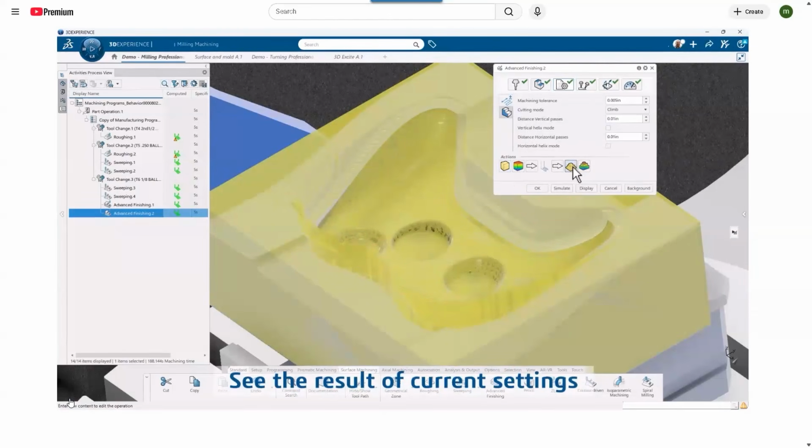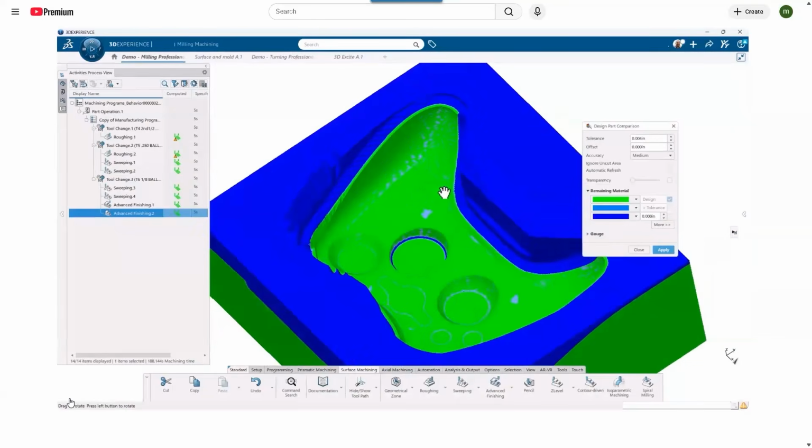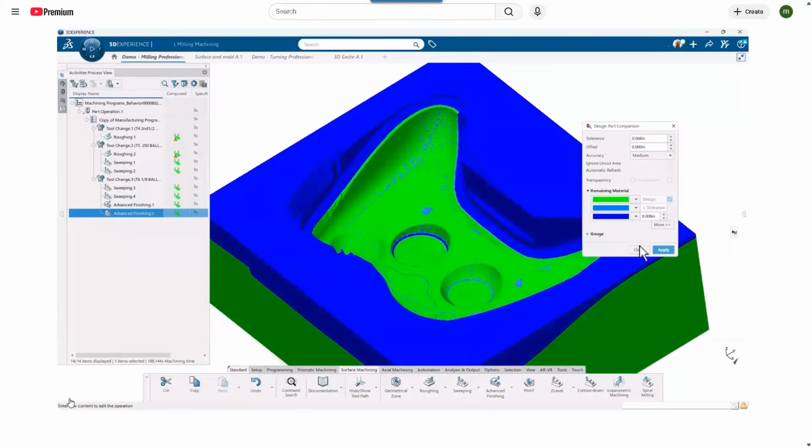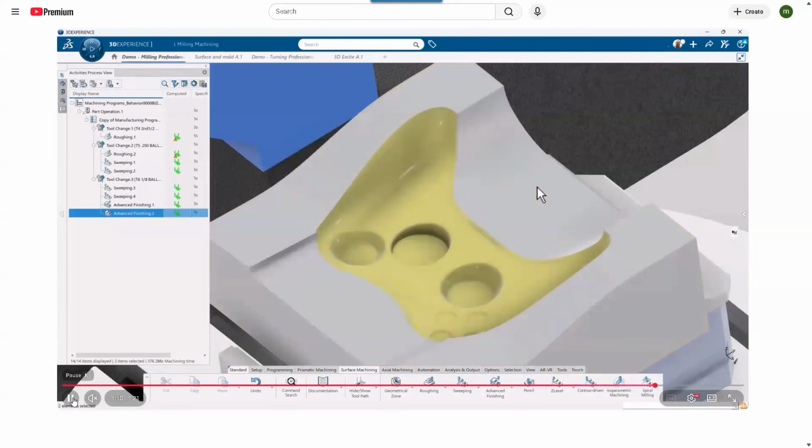On top of it, we have this intermediate stock where we can see all that in real time, so I don't have to watch the toolpath run. I can just click on a button and it'll show me the result: what's coming in, what's going out, where we're gouging, what's the remaining material. So if I'm a person that's in a hurry and I don't want to watch the toolpath run, I can just hit those buttons and do the simulation on the fly, and away we go.